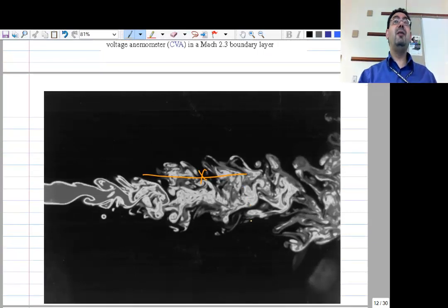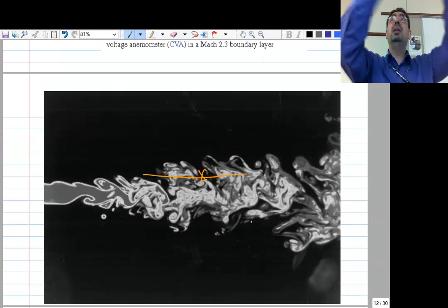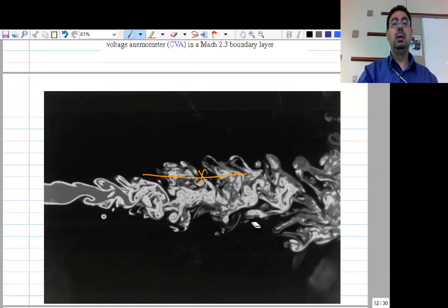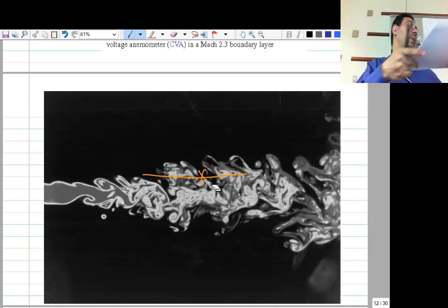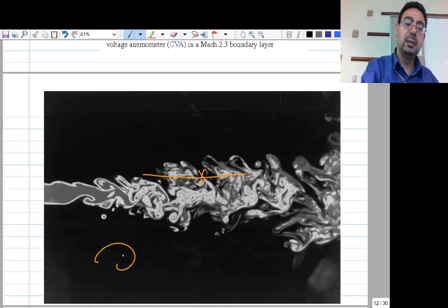So it turned out that every single flow has its own large-scale structures. Okay? So if I introduce a jet in ambient air, there are certain large-scale structures or large eddies. Okay? If I have two shear layers, for example, high flow coming and lower flow, the exit of a duct or something, you are sending the duct into a room. That's also another kind of large-scale structure. They will actually look like this.